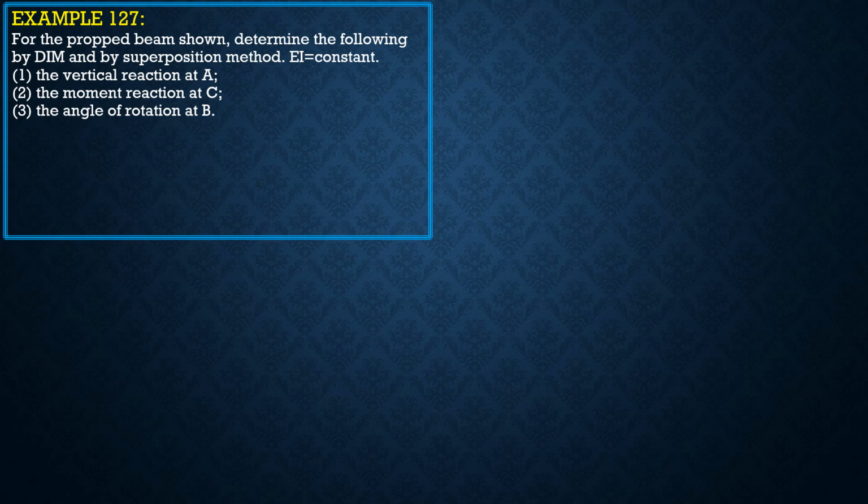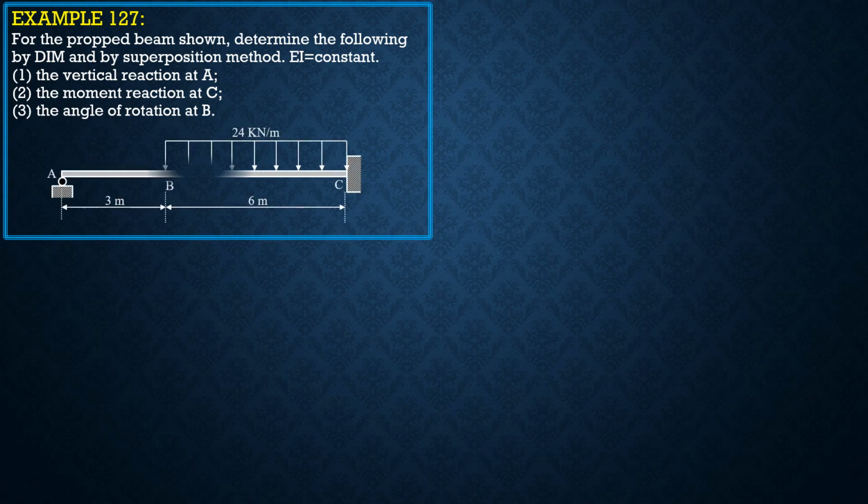So if you can recall, EI theta equals moment at the wall, length over degree plus 1, while EI delta is equal to moment at the wall, L square over degree plus 2. So first, by double integration method.